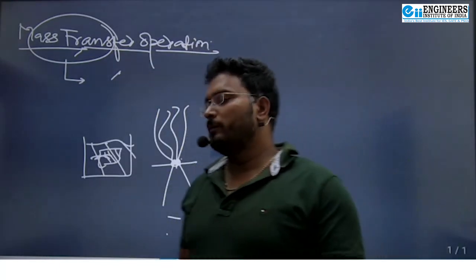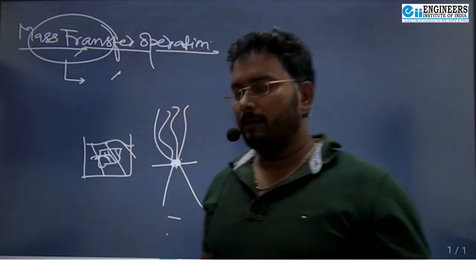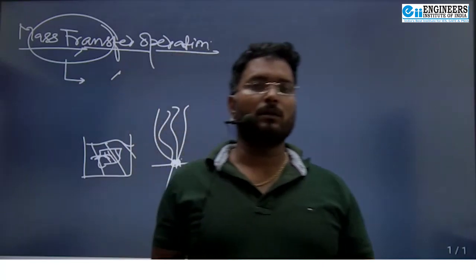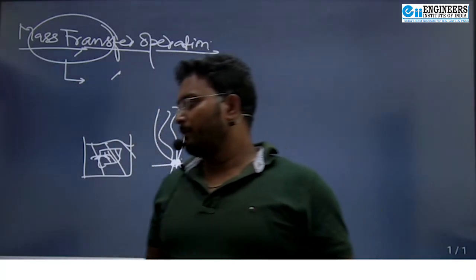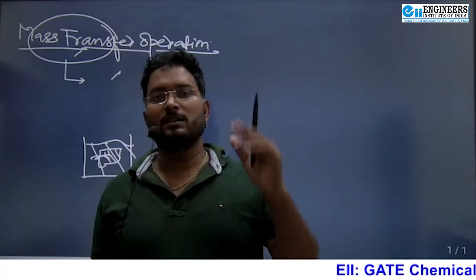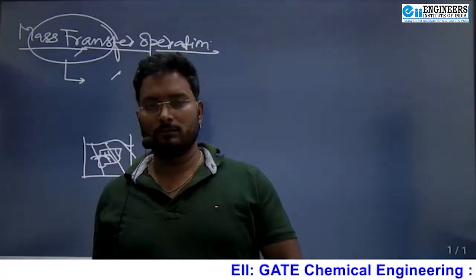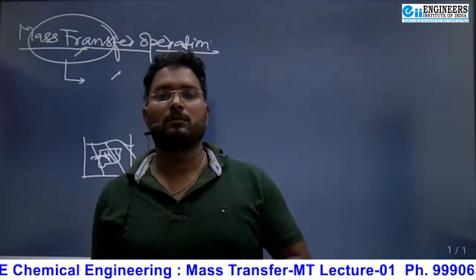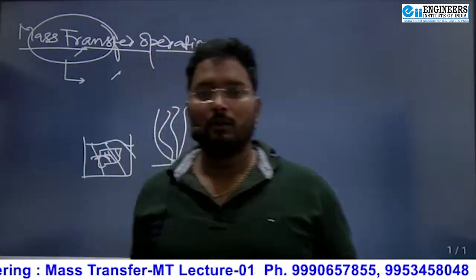And if anyone has done training in an ammonia plant, there are two towers, an absorption tower and a stripping tower. In the stripping tower we are using steam as solvent in order to remove the diethanolamine which gets absorbed in the liquid in the absorption tower.